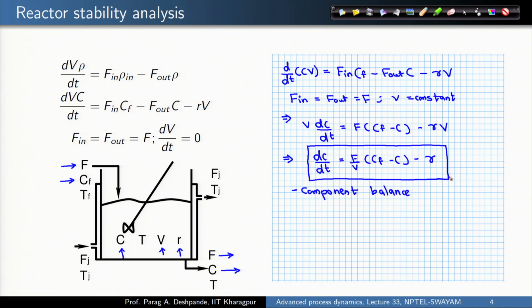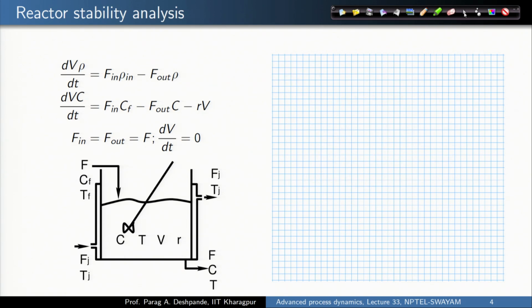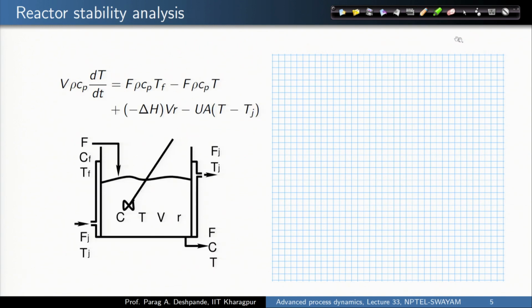The second dynamical equation involves temperature, and to have an idea about temperature, we need to do an energy balance. So, let us look into the energy balance. Now I have a system in which a possible variation of temperature and heat exchange is allowed; it is a diabatic process.